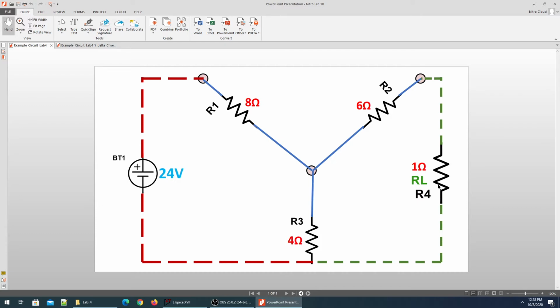What we're going to do next is to find the Thevenin equivalent of this very circuit. Once we're done with finding the Thevenin voltage and the Thevenin resistance, we'll connect the load resistance again, and test the circuit for the voltage and the power rating.